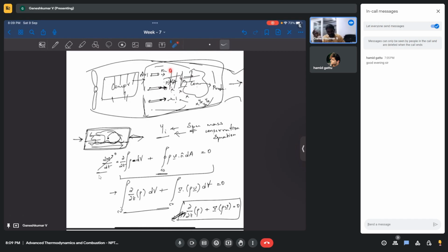So fuel will be higher here, and fuel will be lower in between these things, right? So fuel will diffuse, and air will go the opposite way. So that diffusion will affect the species, how uniform it is. True. So the main thing is diffusion. In addition, turbulence also will affect. I won't say it is a minimal effect, but the major effect is diffusion. Okay, sir. Diffusion of species.